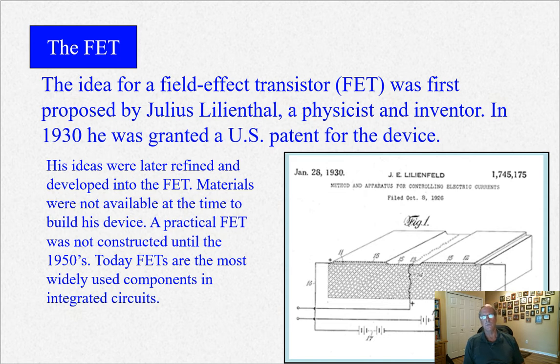But the FET most closely resembles the function of a vacuum tube, because a vacuum tube also has a transfer function, which is a current controlled by a voltage. Unlike a BJT, which is a current controlled by a current.